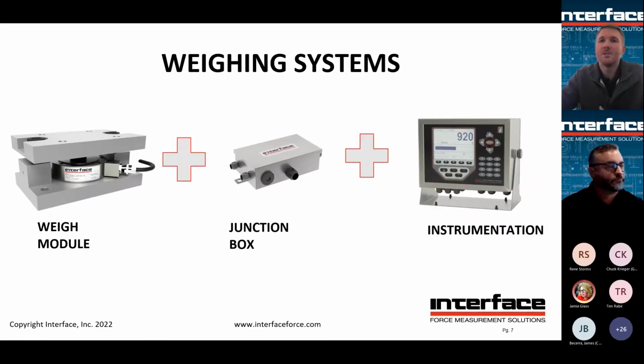So, weighing systems. Here are the pieces that make up a scale or weighing system. It will consist of mounting hardware and of course a load cell. The mounting hardware will offer side checking, be able to compensate for thermal expansion, off-axis loading to a point. They typically come in sets of 3 or 4, but could be up to 12 or more.